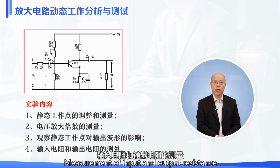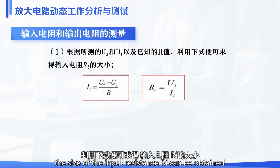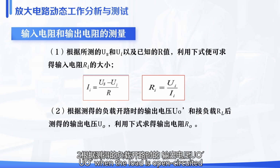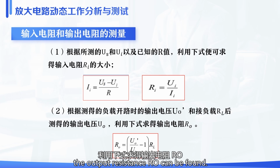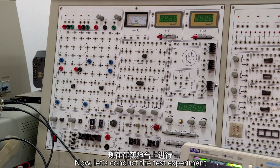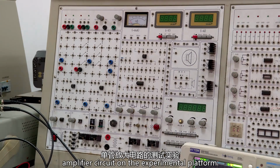Measurement of input and output resistance. 1. Based on the measured current I and the known R value, using the following formula, the size of the input resistance can be obtained. 2. Based on the measured output voltage UO when the load is open-circuited, and the output voltage measured after connecting the load RL, using the following formula, the output resistance RO can be found. Now, let's conduct the test experiment of the single-tube amplifier circuit on the experimental platform.